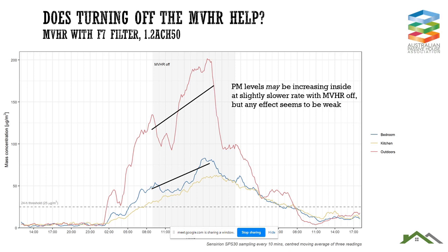So that's obviously only the infiltration through the building envelope, but it's a fairly weak sort of a relationship, and because the PM levels are continuing to increase indoors, and we weren't really generating any indoor PM on that day except perhaps a bit of walking around, which does stir up some stuff, it doesn't seem that that of itself will be sufficient, certainly not in a building of this level of air tightness, to avoid these events.